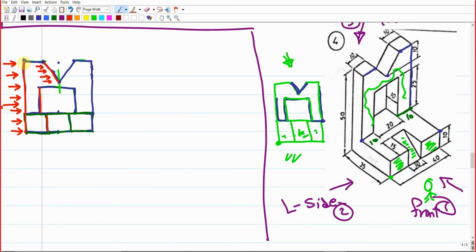Okay, like this vertical line, and remember there should be another edge here over it. And there is another vertical line, and inclined line. Your objective is just to project these lines on the side view. Project how? From the start point, draw a very light line that is barely seen. From the end point, draw a very light line that is barely seen.